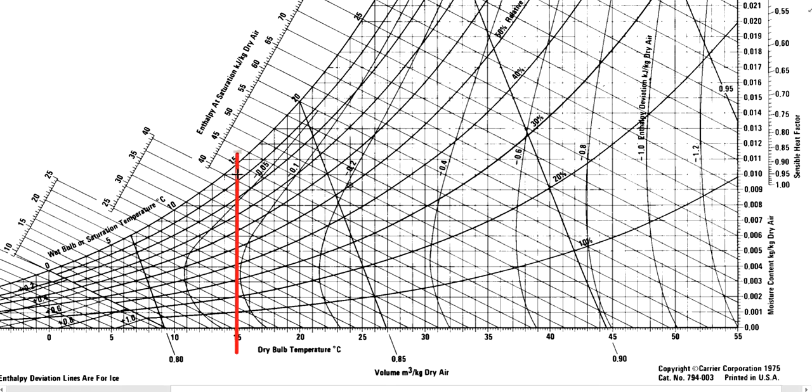So here's the 15 degrees, and we have 13 degrees wet bulb. Here's 10, 11, 12, 13. So here it is, this is our state 1.